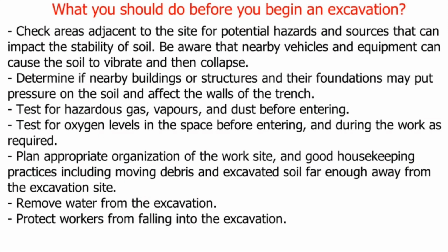Plan appropriate organization of the work site, and good housekeeping practices including moving debris and excavated soil far enough away from the excavation site. Remove water from the excavation. Protect workers from falling into the excavation.